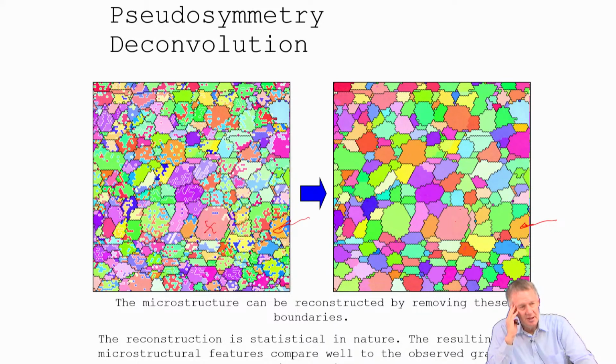For the superlattice, typically you're right that it would be somewhat of an ordered structure. But if you consider something with a lot of solutes in there, it doesn't necessarily have to be an ordered structure. Usually it's one specific type of atom that is breaking the symmetry or giving you something different, and it's usually in a specific position within these additional cells, like what I was describing before. So usually that's what gives you that superlattice structure. So a superlattice has less symmetry than the disordered one? In every case I know of, it does.